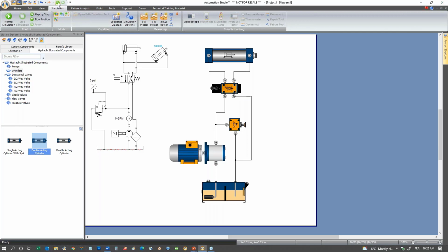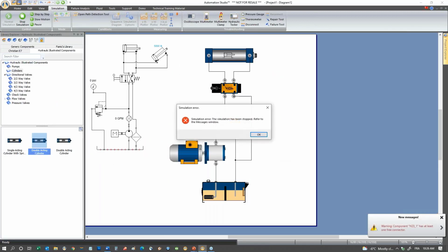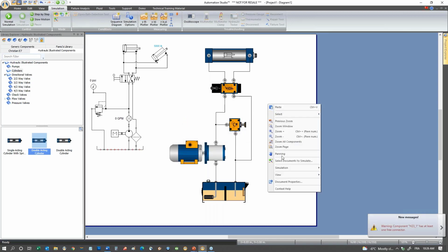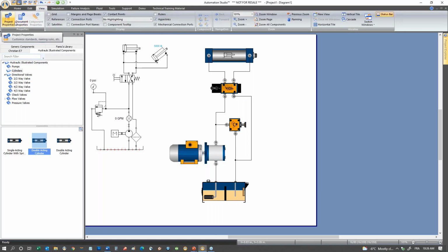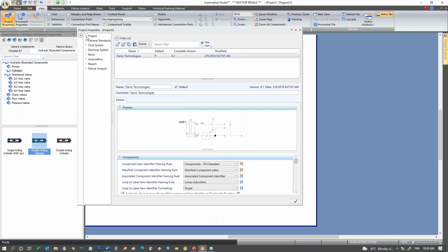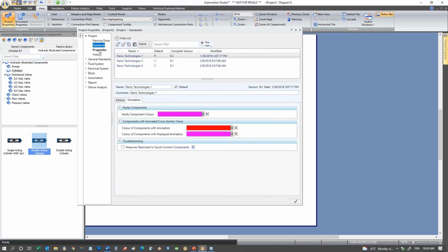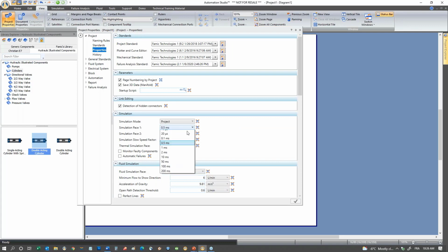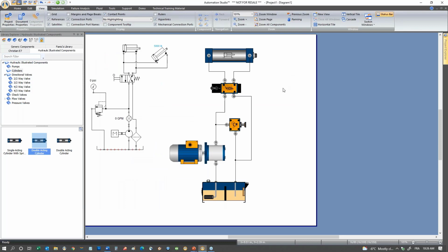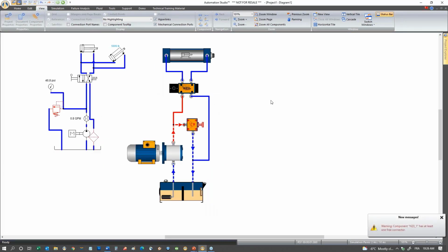So now when I simulate, oh, sorry about that. It's just a matter of simulation pace. Sorry about this. In the document project properties here, our simulation pace is a bit too quick. So hold on, it's here in the simulation. I just need to go to about 2 milliseconds, because with our electrical module, we've added more precise simulation, so we have a better response. But for some of the modules, you just need to go back and use a more regular simulation pace.